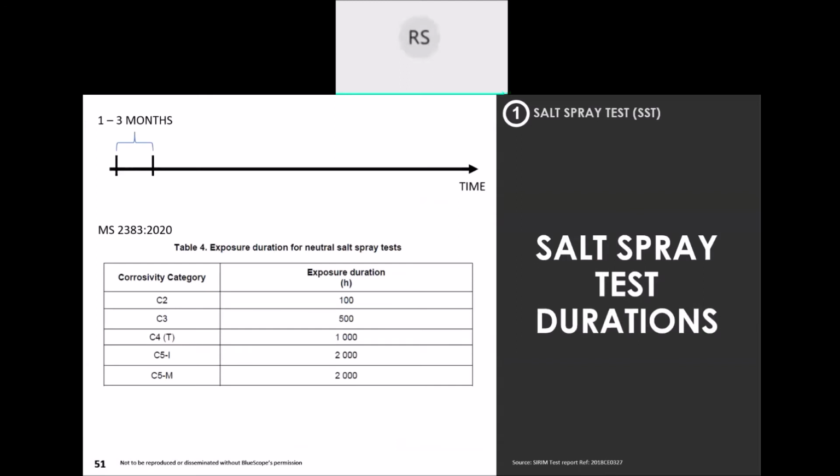All right. So of course, if you look at this standard, this is for coated steel testing standard. What they attempt to do is correlate the salt spray test to a certain corrosivity category, right? But this again is not very reliable because this has been copied from a very traditional testing method and an old reference document, which actually implies that it's not really relating to actual performance.